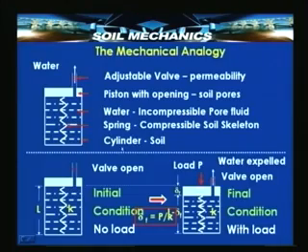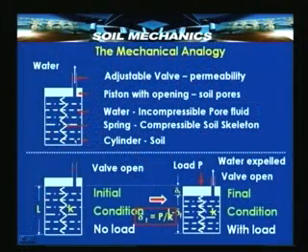So, if clay is represented by this entire cylinder containing water, then presence of water contributes to the saturation effect. Then there is a spring which is nothing but the entire skeleton, the overall skeleton, which includes the particles, the void spaces, and it is capable of compressing when the water goes out.